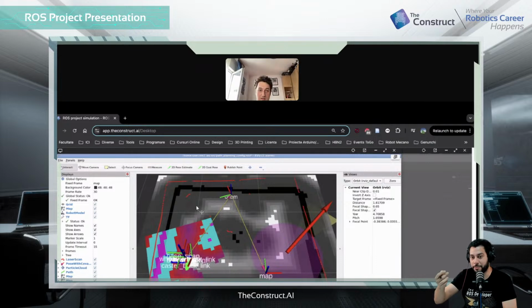Right, it makes sense, and you can actually change that. So you go to the YAML, and you want to change that map origin, that frame. You can go into that YAML and just put 0,0,0, and it will be at the start of that PGM. But unfortunately, just so you know, you can't rotate it, because otherwise the cost maps won't rotate with it. You need to go into the nav2 source code and basically rotate those cost maps as well.